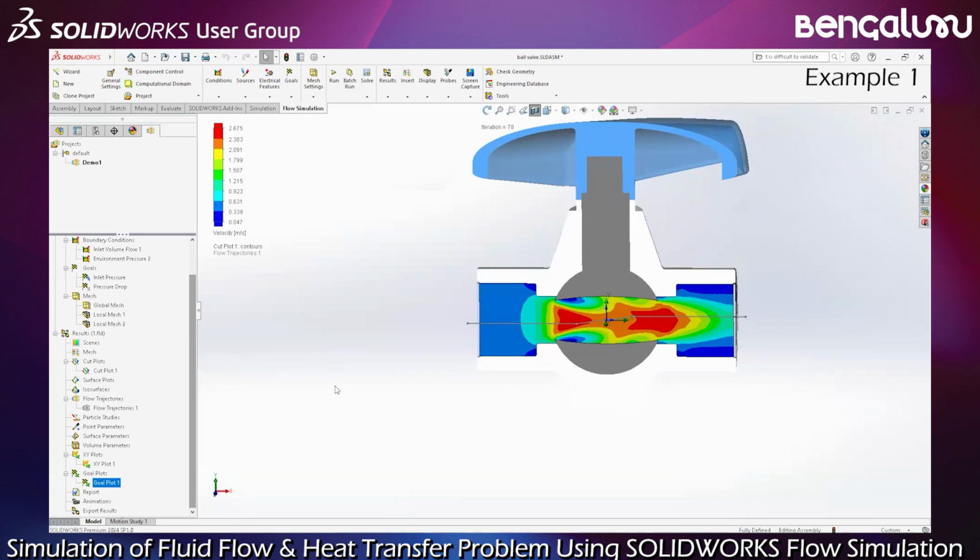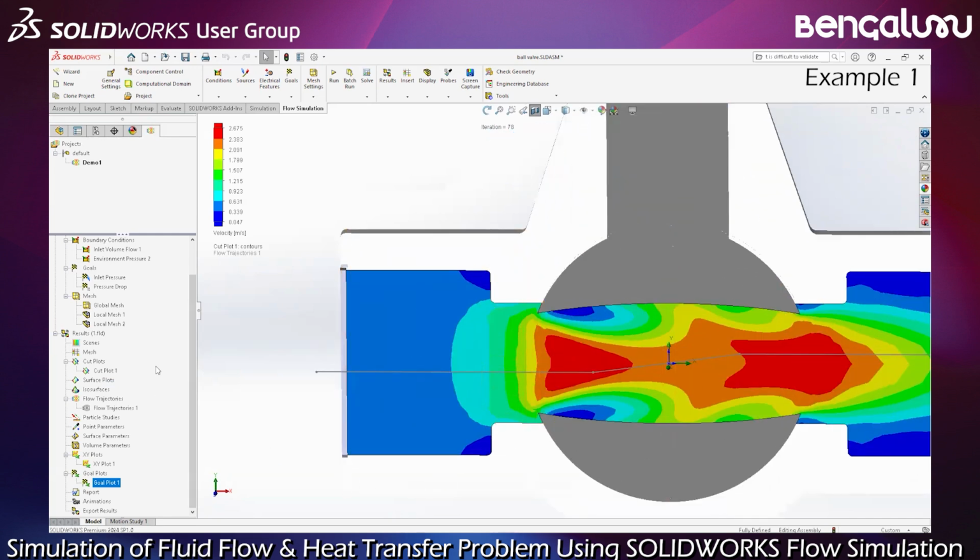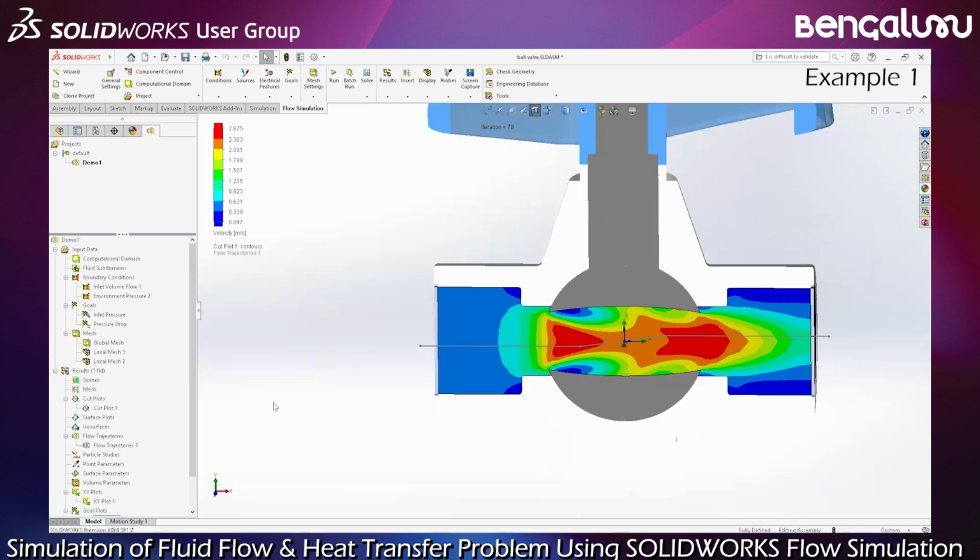If I need more accuracy, I have to pay attention to the mesh. Does it catch all the details? And why do I have to pay attention here? Because of the restriction, the shape of the geometry, the sharp area, I have to catch it with the right mesh. Otherwise, the calculation could be less accurate. You need to represent the geometry features with all the details possible. This is why changing this could result in better accuracy.